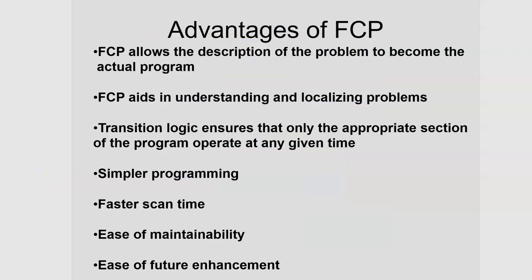And then of course there's advantages to this type of programming. So I'll be familiar with these advantages of function chart programming. We'll go through it. Function chart programming allows the description of the problem to become the actual program. So you remember in the first couple slides where we had the problem, where we were making the widgets, and we had to actually list out the steps. The listing of the steps, each step became kind of a mini program. So just understanding the problem helps you design the program. So that's a big advantage.